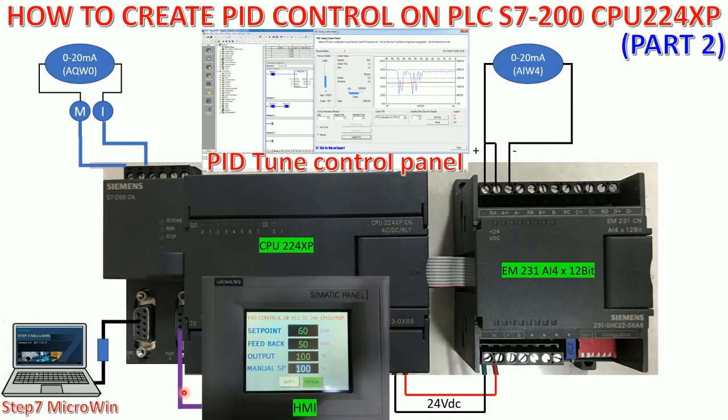For today, we will create the touchscreen HMI, like setpoint, feedback, output, and manual setpoint, and a button for auto and manual mode control from the HMI.